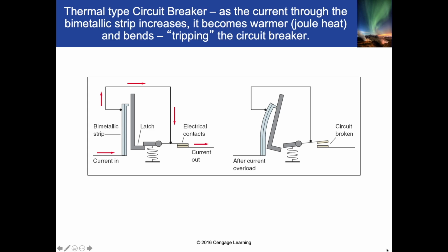But the thing is, if you have all those things, including your air fryer in there, it gets really hot. The thermal expansion of one of these metals, probably this one right here, the one on the left side, is larger, so it gets to expand a lot more. And when it does that, it bends. And when it bends, it pushes this little L-shaped thing here, the latch. And when it pushes the L-shaped latch, this little spring right here releases, and then you release your circuit breaker. And that's why you lose power in part of your house, right?